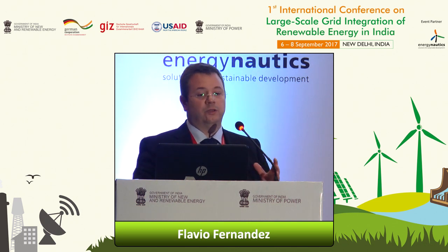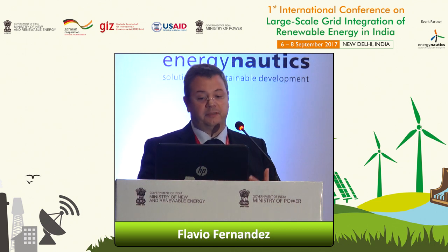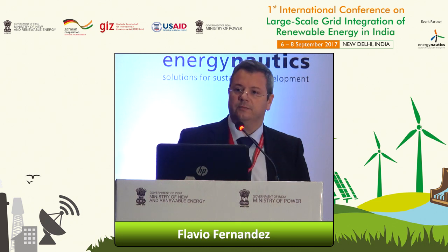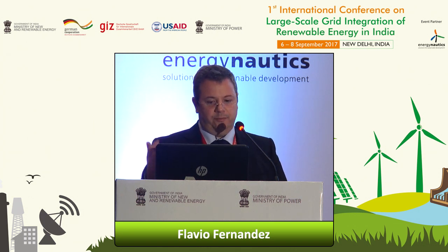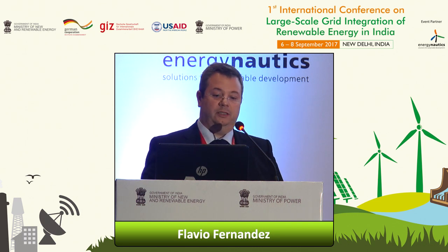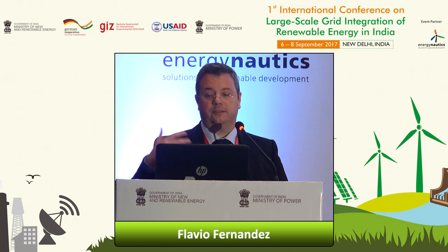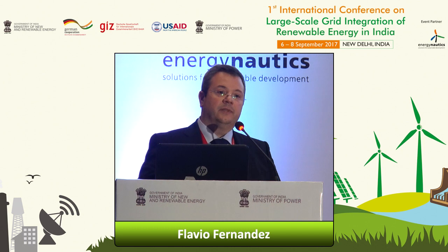the different models, from manufacturer-specific to generic standard, are both okay. The manufacturer-specific ones are typically black box, the other ones are open-source models. What is important in terms of simulation is that they have to be fit for purpose, so we need to think about what we want to do with the model. Simulation performance is also an important issue, and then the portability of the model, and you can work on these two things, either to promote the use of generic models, as we do for conventional power plants, or if you go for manufacturer-specific, you have the IEC standard. And finally, an outlook.